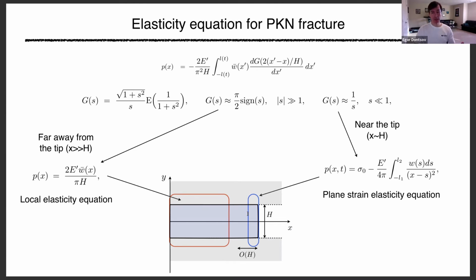Now, the reason I'm telling you this, what's the main purpose? The main purpose is to construct these fracture regimes. We need to know when toughness dominates, when viscosity dominates. If you take the classical PKN model, there is no toughness in it, right? It was developed assuming purely viscosity-dominated propagation. So we cannot just use the classical PKN model, because if there is no toughness, how can you have toughness domination, right? And so the question is, how do you account for this toughness? That's the whole thing I'm showing you, to understand how we account for toughness, okay?